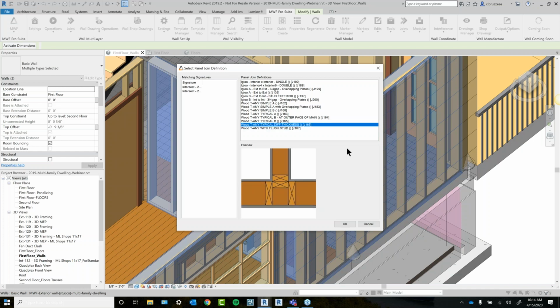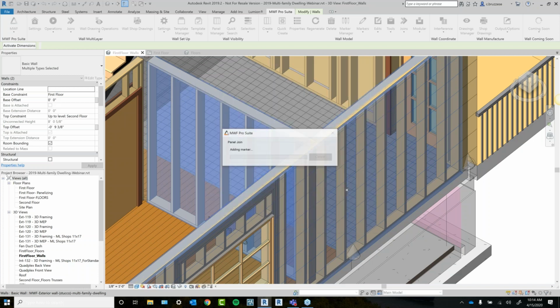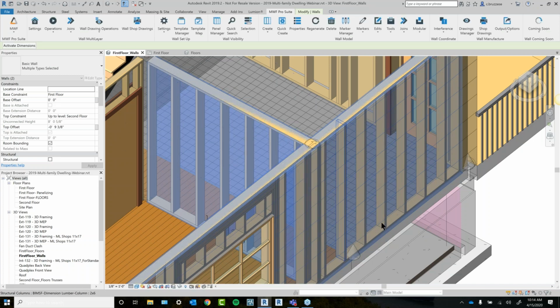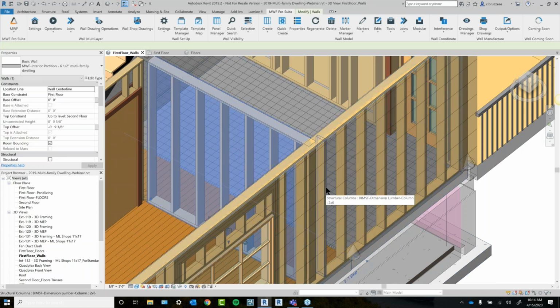These are the main ones that I can pick, in this case, for my T intersection. I can place it manually and go through connection to connection, and then it'll auto-generate with whatever join I've selected. But what I'm going to focus on is creating a rule for those joins to follow.